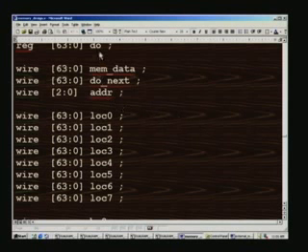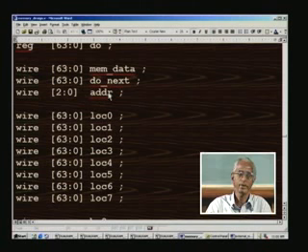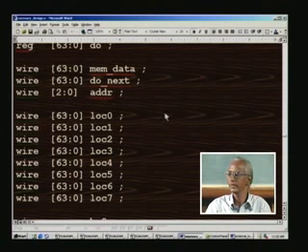And as in ROM we are using lots of internal signals and of different bits. That is what we have listed here, and address is also either read address or write address. So a common address is invoked here, and width is 3 bits because we need to address only 8 locations. And as in ROM design we will have a location 0 through location 7 here, and they are all combinational circuits, therefore they have been declared as wire, and width obviously is 64 bits here.